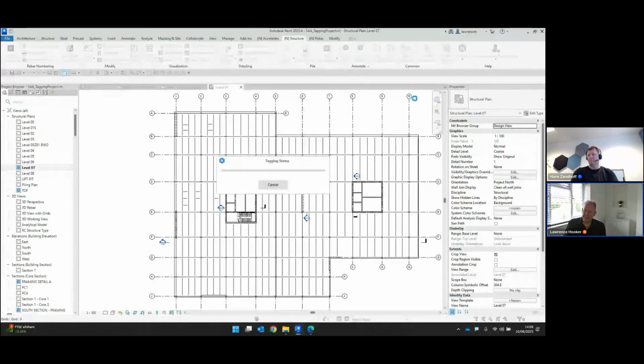columns. Now, as it does this, notice in the top left-hand corner and also on the left-hand side of the project here, in between grids D and E, we have all of these trimmer beams. And of course, Revit would just ignore those and all the tags will clash, okay? Because Revit, by default, will put the tag in the center of the element. But you'll see Naviate will then use a linear placement and a tolerance to allow that tag to move up and down or left and right along the beam so it doesn't clash.